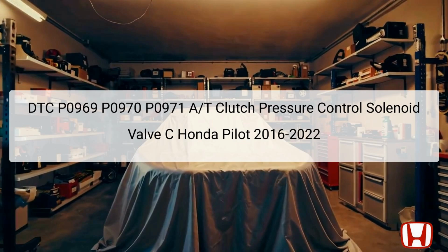Diagnostic Trouble Codes, DTCs, P0969, P0970, and P0971 specifically relate to issues within the automatic transmission, AT, clutch pressure control solenoid valve C of the Honda Pilot models from 2016 to 2022. The clutch pressure control solenoids are crucial for managing hydraulic pressure in the transmission, thus affecting gear shifts and overall drivability. These particular codes indicate performance anomalies, low input or high input issues related to the solenoid valve's operation.